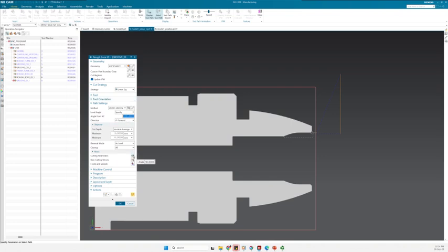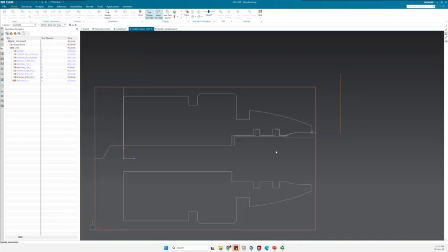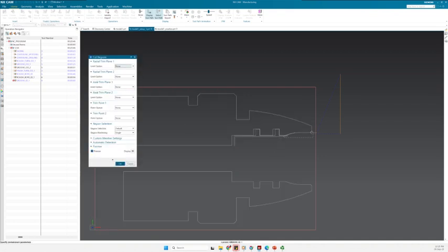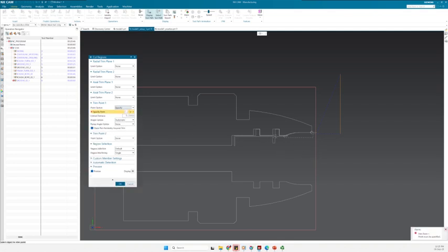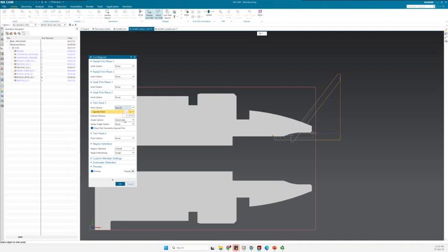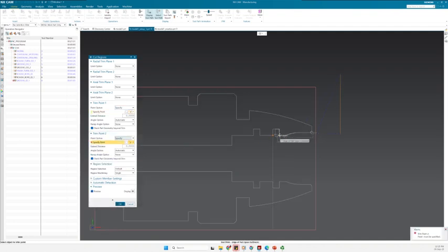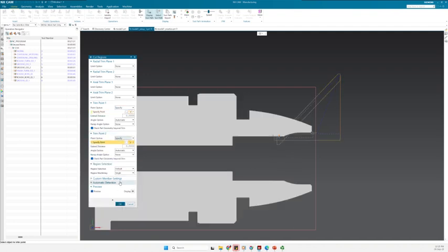Then after that, I will have to define the cut regions. I will define the cut region for the groove itself on top of the crown, as it was said earlier. So it is in contradiction with the outside groove. And then I will use trim point 1 and trim point 2. Trim point 1, I will specify this one, and let's say I will choose this one, and for trim point 2, I will choose the crown one.